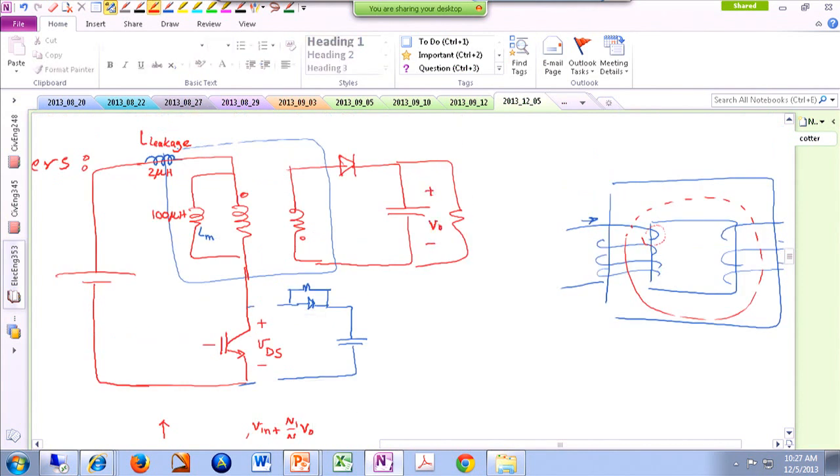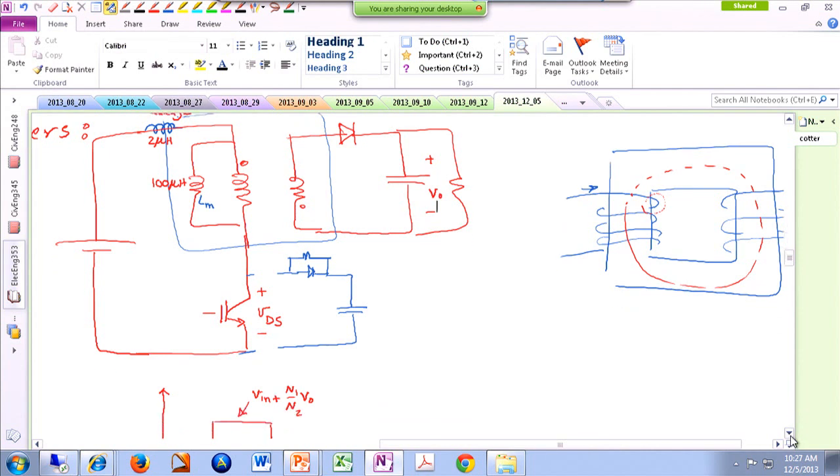Okay. Now, if you consider this leakage inductance existing, what happens is when you open up the switch, we have current right before that. You have current here and here. For this current, no problem. It circulates around here, and that's actually how we analyze the system. So no problem for the current of the magnetizing inductance. But for this current, it has nowhere to go. And what it does is, well, you definitely have some parasitic capacitance around your switch.